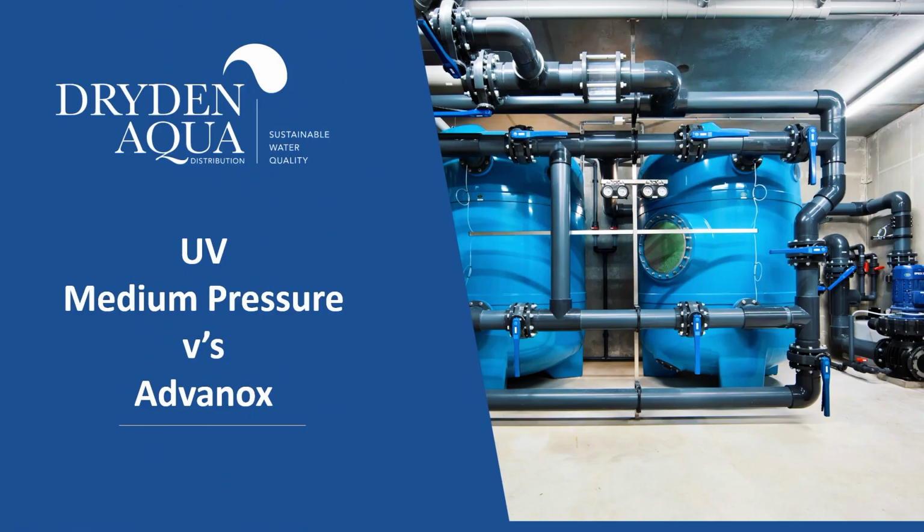I would like to compare now medium pressure UV versus our Avanox system, because medium pressure UV is often recommended in the UK, first of all, to create a barrier against Cryptosporidia, because it will inactivate Cryptosporidia, but also to take out combined chlorines. But there is a side effect to that. With AFM DAISY, we create a barrier against Cryptosporidia, so it negates really the need for medium pressure UV. But we still get a build-up of organic chloramines in the water that need to be dealt with.